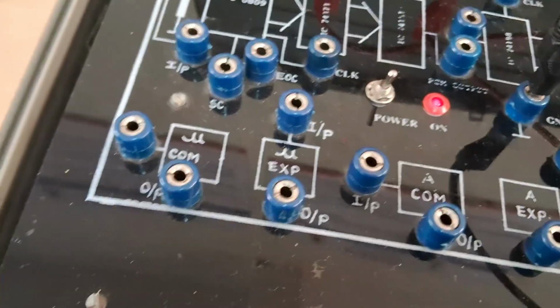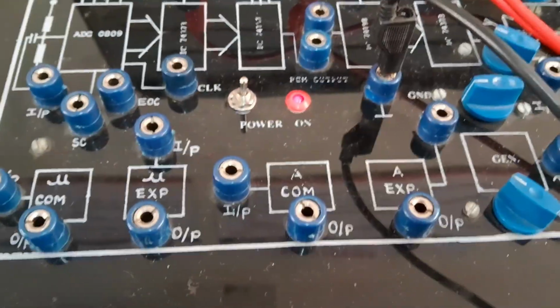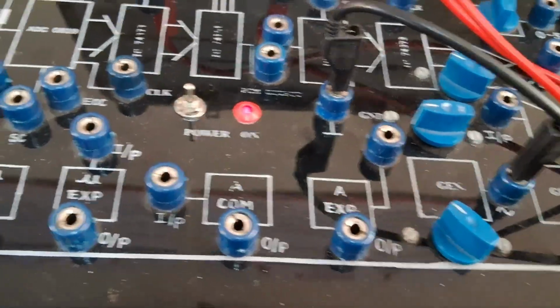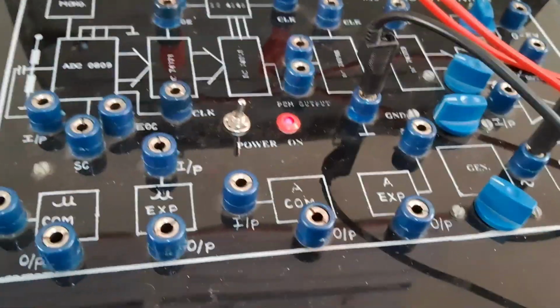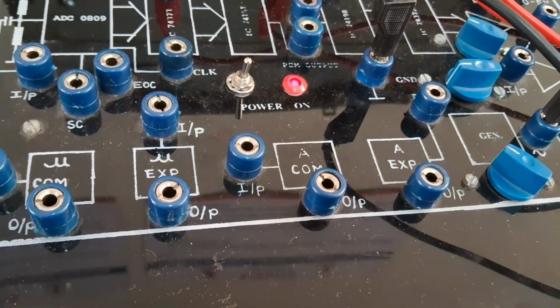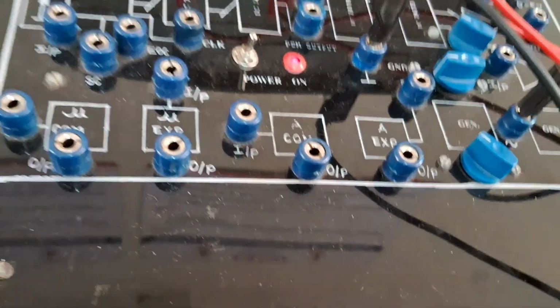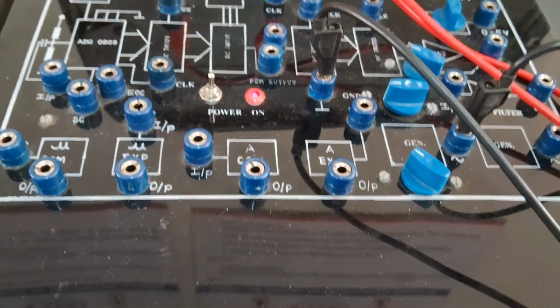Now what is companding? During quantization there is an error which exists in the PCM. So the signal to noise ratio of the PCM system goes low. To increase the signal to quantization noise ratio of PCM, we go for the companding process, where the signal is compressed at the transmitter end and expanded at the receiver end.